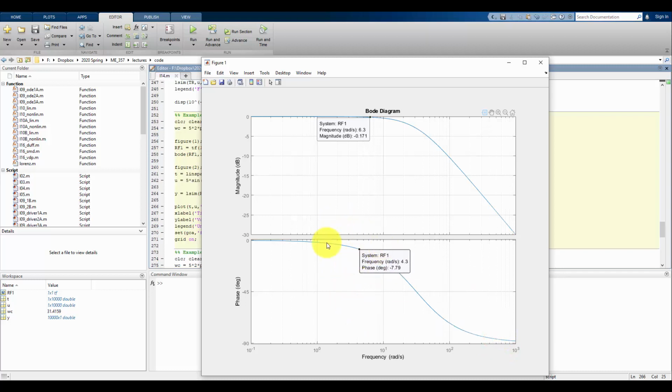So again, for the signal that we want to keep, the stuff that's below the cutoff frequency, we are introducing at those frequencies this small amount of lag that we want to be aware of, that we're going to have a little bit of a time delay once we go from the input of our filter to the output of our filter.